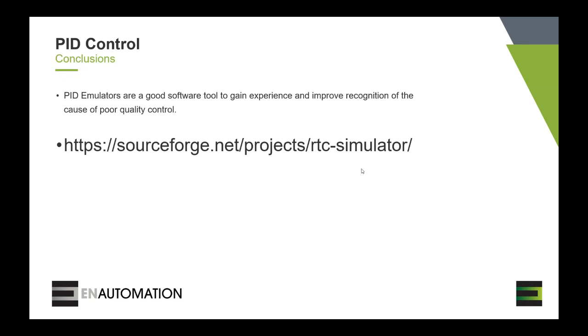I see there's a couple of questions. So one question was, must one measure process response time ahead to design the PID? Design-wise, no. Tyler's going to talk about some of these examples. But certainly before tuning, it's always important to know what the response time is. The PID controller will look the same regardless of the process response time. The way it's implemented in logic, it will look the same.